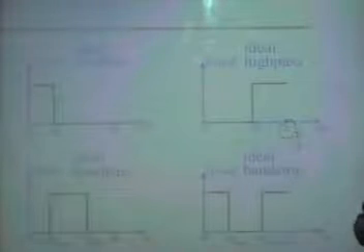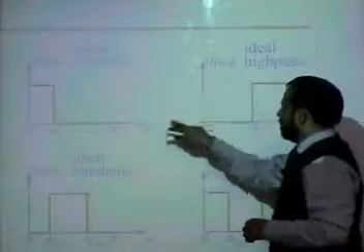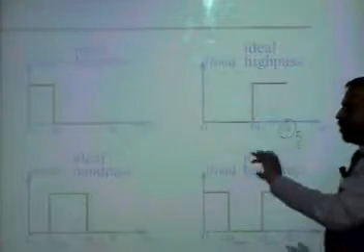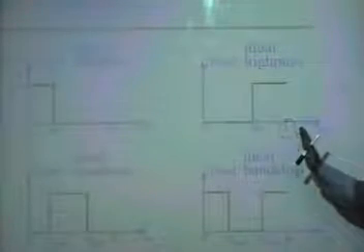It obeys the Hermitian symmetry, that its magnitude response is symmetric around the axis. So you don't plot it. Why waste space, because you're going to see the same thing on this side. So in this book, whenever it is a real signal or a real system, it will only show you half of the spectrum, because the rest of the spectrum is similar to this spectrum.